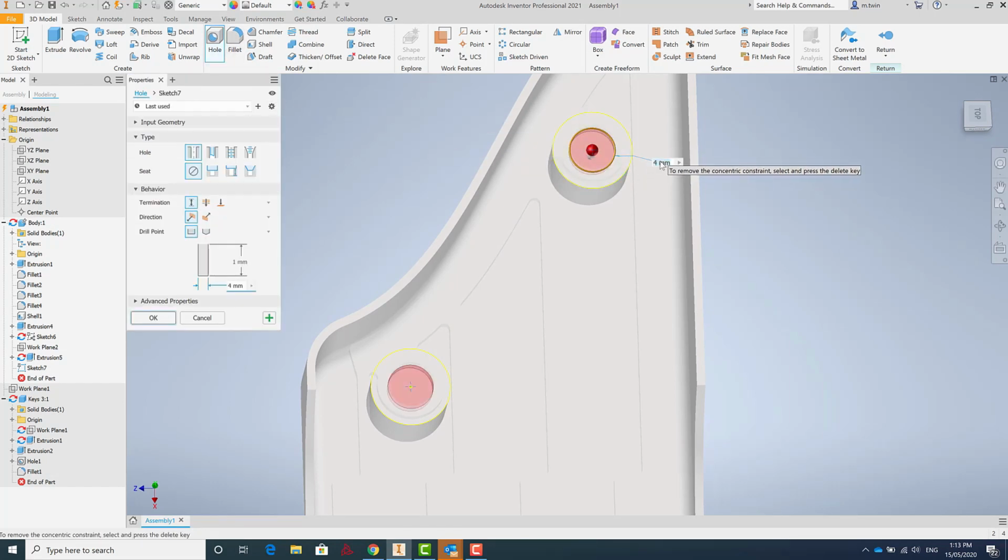and this time I want to create a smaller hole. I think I will create a 3.7 millimeter hole, and oh wait, no, 3.2 millimeter hole, because I'll actually try and thread these with a tap and get those in there.